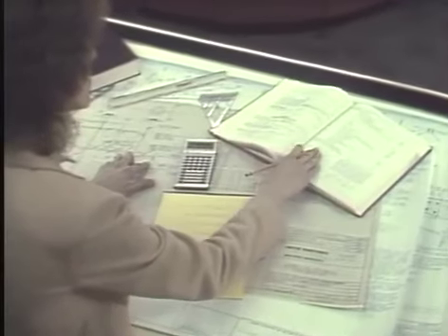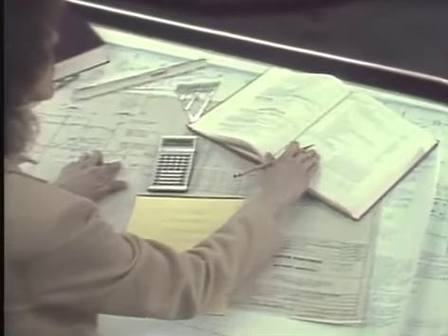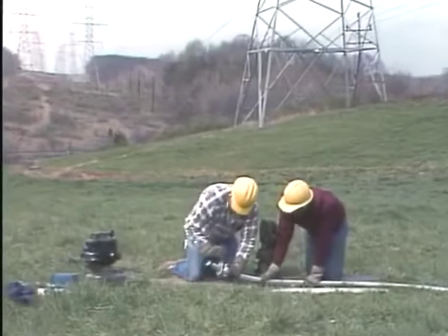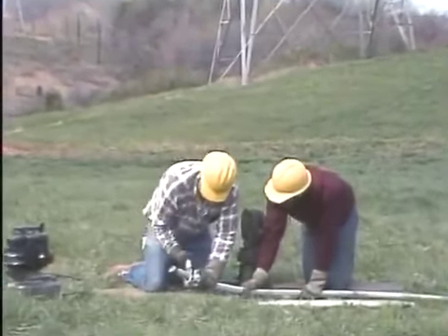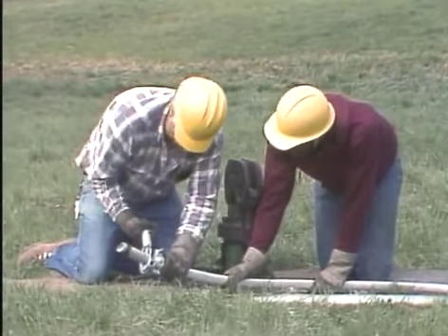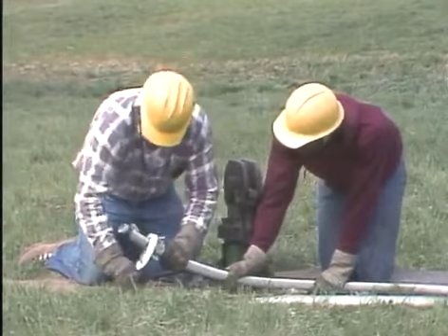You must ensure that these systems are installed and maintained according to design specifications so that all the preventive measures established on the drawing board are effectively put into action on the line. This includes things like making proper installations according to design drawings and making good conductor connections to maintain reduced resistance and power loss. You should follow your company's procedures for crimping and cleaning conductor connections and splices.